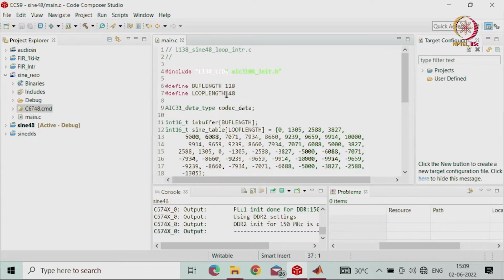The other one is DMA based. There, CPU intervention is not going to be there, directly from the memory you will be reading into your memory to work on it. In some cases you may have a frame length of whatever length you have given, so you can directly read from the memory and then put it into the local memory.